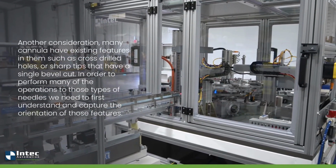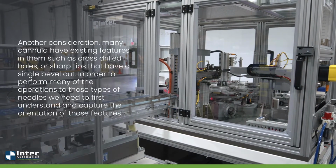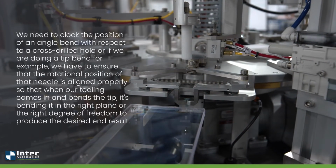There are also considerations that many cannula have existing features in them, such as cross-drilled holes or sharp tips that have a single bevel cut. And so in order to perform many of the operations on those types of needles, we need to first understand and capture the orientation of those features. So we need to clock the position of an angle bend with respect to a cross-drilled hole.